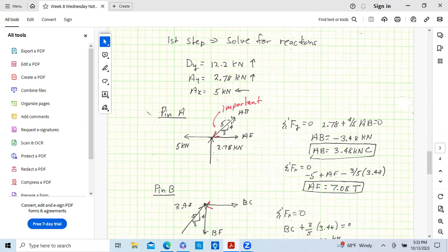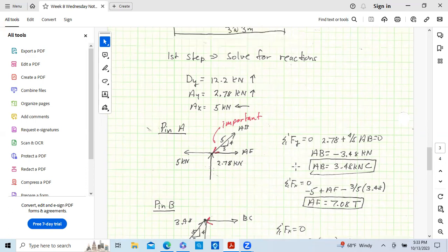So I have this as tension, and I draw this as tension. If it's not tension, it's compression. So from this point on, the rest of the truss is incorrect, because you're going to treat this as a positive y and a positive x. Compression. But you have to keep track of this, and here's how I would recommend you do it.